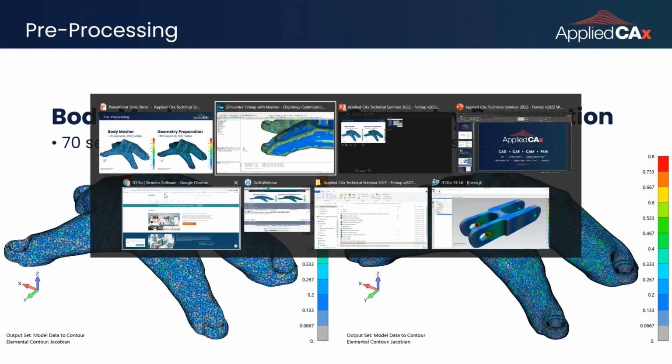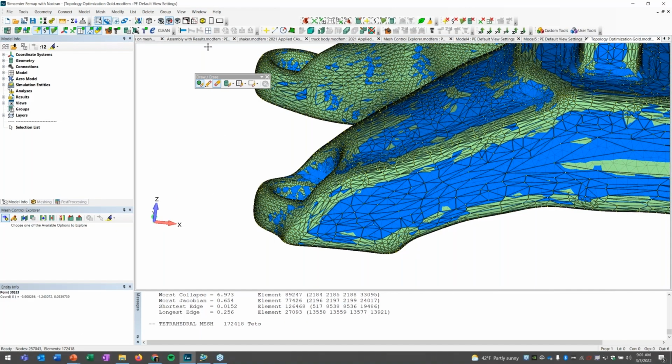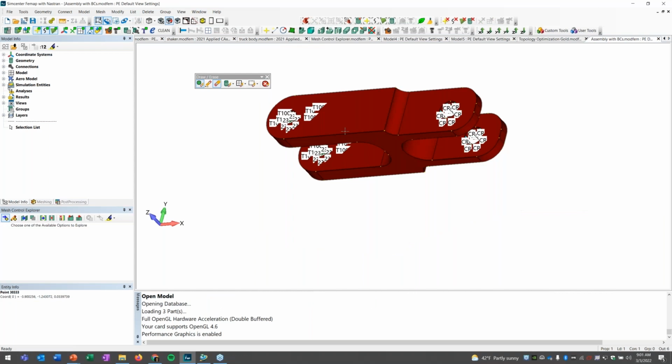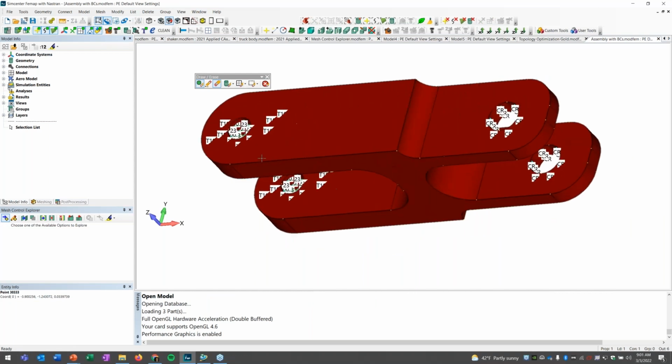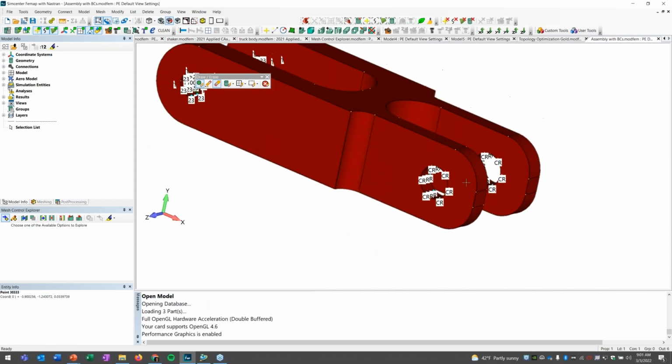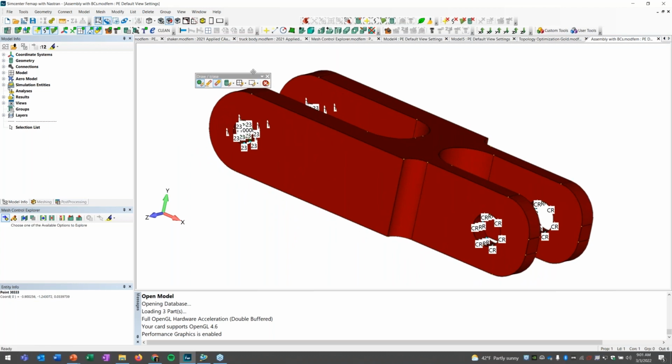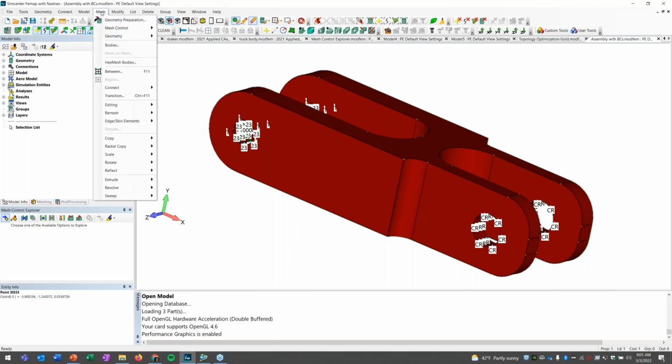So what I had done as a simple example is this assembly here. I went through and applied my boundary conditions first. That way I know on these surfaces here, on these curves where I've applied these loads, that this tool, this body mesher, which is really hex mesh bodies or tet mesh bodies, same approach, isn't going to pave over those details. So let's do this again.